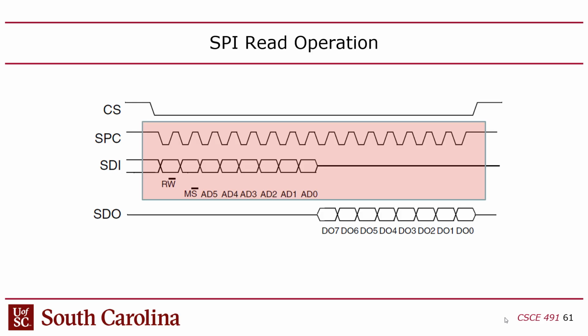So if I give you a timing diagram on a quiz or a test, and I ask you whether it's a read or write, it's very simple to figure that out. You know just by looking for these dead zones, right? If the MISO is dead the whole time, it's a write, because nothing is sent back. And if you have a split where MOSI is dead for the second half and MISO is dead for the first half, well then it's a read, it's a load. You don't have to look very closely to figure that out, right?